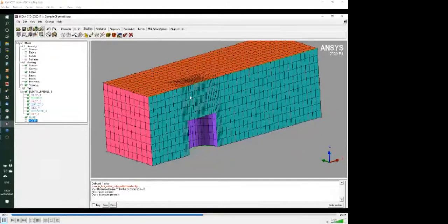If you're going to try and do the same thing with an unstructured mesh, which cannot take advantage of topology, and I'll demonstrate unstructured meshes now for the rest of this video, then you would probably need well over 1 million cells to capture the same accuracy. So there's a lot to be said for structured meshing, but it is very tedious. It needs a lot of expertise to do it well, and it is becoming less and less common. There are certain applications such as turbo machinery where it's still very well used, and then you often have very specialized software to make the generation of such meshes more convenient.